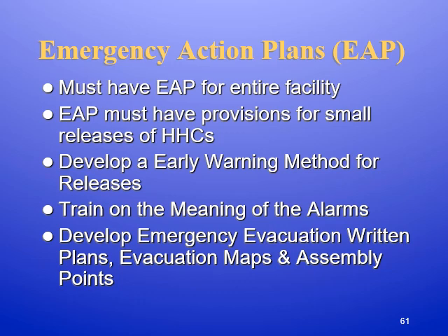Emergency action plans, EAPs. There must be an EAP for the entire facility. EAPs must have provisions for small releases of HHCs, develop an early warning method for releases, train on the meaning of the alarms, and develop emergency evacuation written plans and evacuation maps and assembly points.